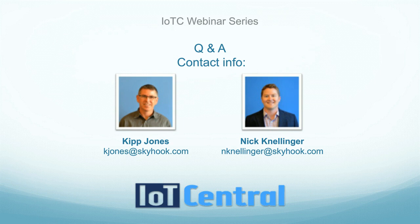How accurate is Wi-Fi location technology? I'll jump in. Yeah, that's a great question. We obviously get that one all the time. We've historically been focused on global support and global penetration in terms of coverage for Wi-Fi. So from that perspective, you're looking at, on average, with the statistics, 20 to 30 meters accuracy over the world. In terms of signal propagation, if you do a survey of an environment, you're talking 3 to 5 meters. So if you know exactly where APs are positioned, you survey them or get their exact location, not crowdsourced, you're talking about 3 to 5 meters.